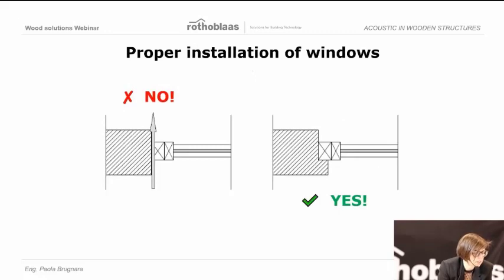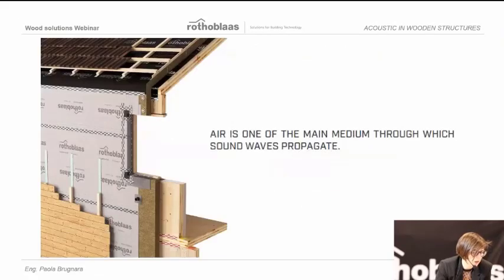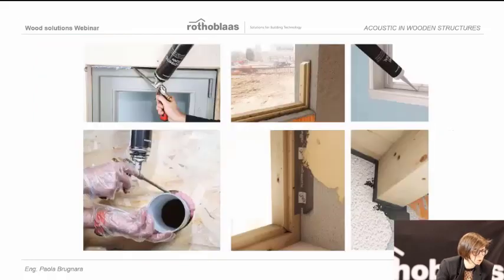Of course, the installation matters, and be careful about the details. For example, installing the window, avoiding a direct passage of the air, will increase the acoustic performance of the partition. Because I would like to remind you that air is one of the main mediums through which sound waves propagate. So, of course, also the installation of the window matters.